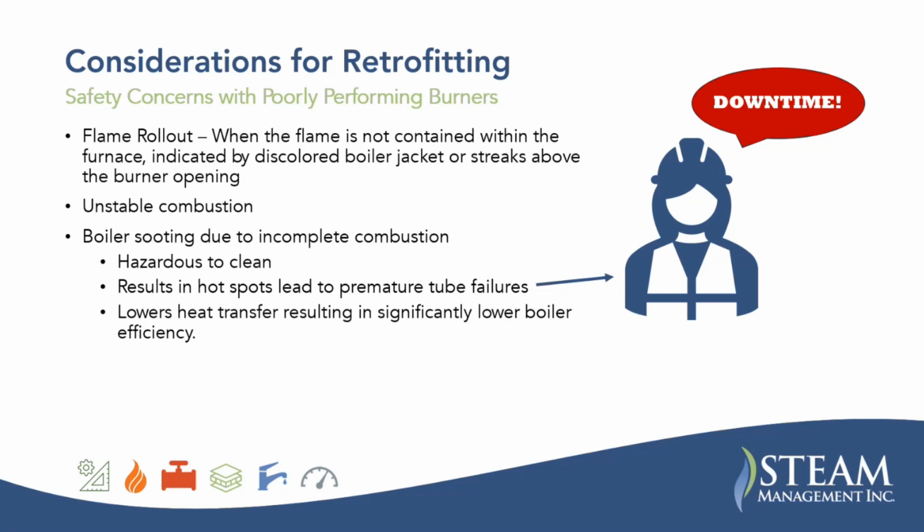Boiler sooting due to incomplete combustion is hazardous. Again, you're making hot spots in your boiler, which can lead to premature tube failures. It's very hazardous to clean. You generally are going to have a professional come in and do that. It's not recommended to try to do it yourself.